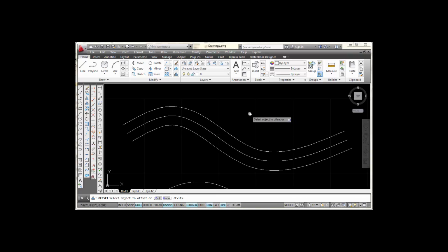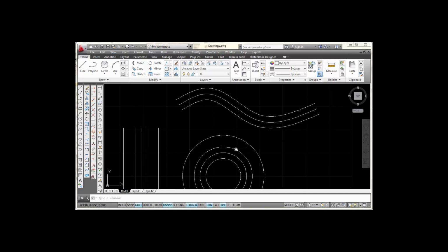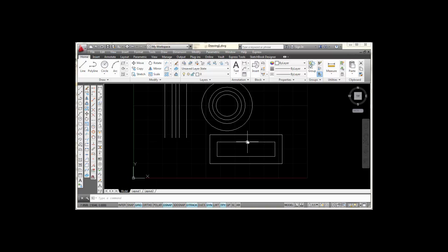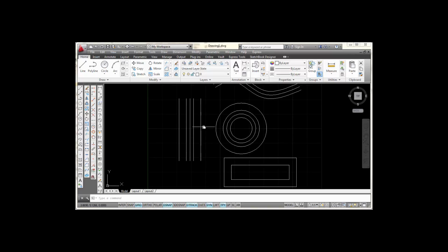I want to show you something about this. You may notice that the top spline looks a little bit longer than this spline. That's because it actually did create a parallel copy, so it moved straight out at a 90-degree angle relative to the end point here, and it moved parallel to this line at a 90-degree angle. The same thing happened on the bottom one. It offset at 0.25 in this direction. So sometimes as you offset things, just like with circles and rectangles, their sizes actually change as they offset. When you offset a line, though, it's going to remain the same size.